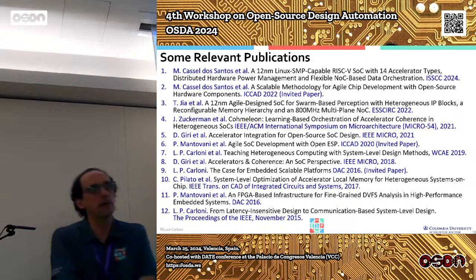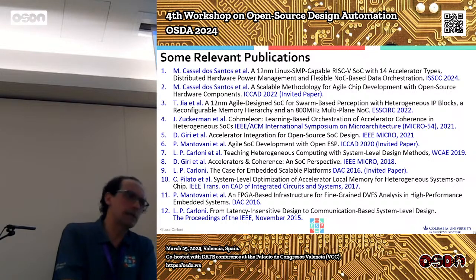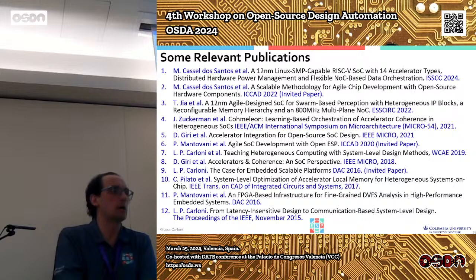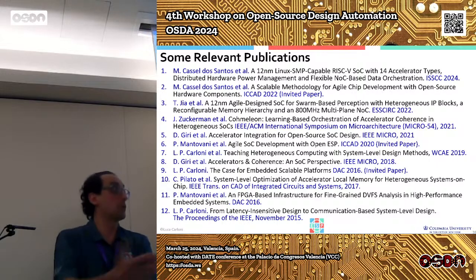But now we have people that are interested in using ESP for a simpler system, which probably doesn't boot the OS and maybe not even an RTOS. Probably they do bare metal. In those cases, you may use a very simple processor. It may still be helpful. I guess you could imagine using ESP without a processor. That would require a little bit of extra effort because some of the things that we provide in order to easily integrate accelerators, whether bare metal or not, would probably have to be adjusted.